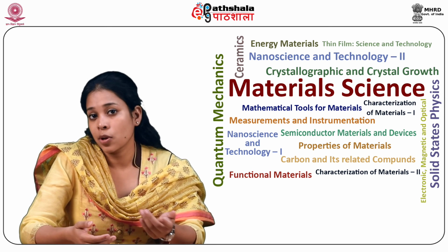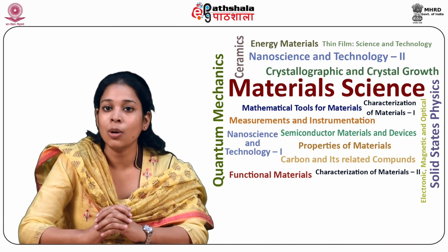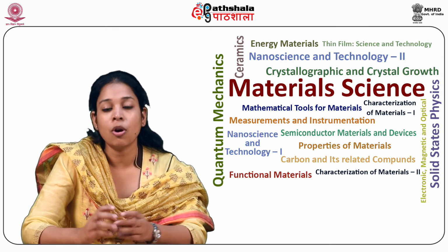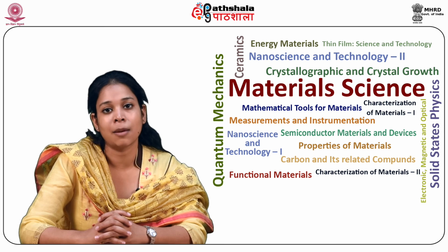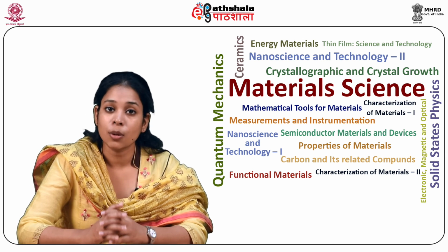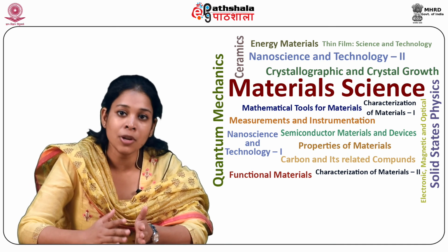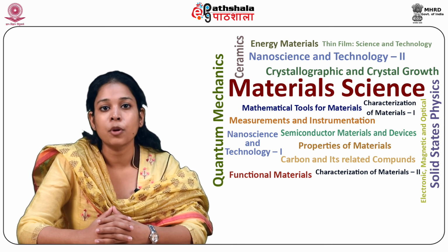The factors responsible for the stability of the tetragonal phase in pure zirconium oxide below a critical size are: first, the lower surface energy of the tetragonal phase; and the multi-domain structure of small tetragonal particles and the presence of coherency strains in the particle. Next, zirconium oxide particles in a matrix such as alumina lead to toughening due to the stress induced tetragonal to monoclinic transformation in the stress field of a propagating crack.